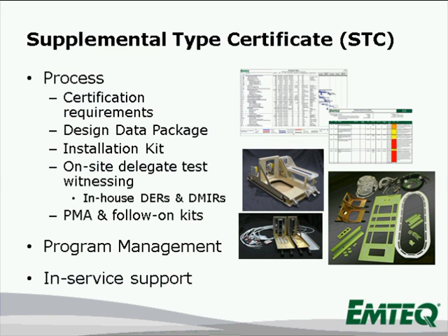From there, what we typically do is we request aircraft data from the customer for their fleet, and we develop a design data package. So we take the baseline aircraft configuration, and we take the equipment data, so the technical data on some of the systems that we discussed, and for the various components, the ACARS, the VHF, the CVR or data printer, and then the position source, and we integrate that together and create a design data package that shows the customer how to install the system in the airplane.